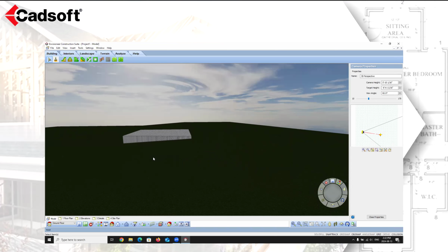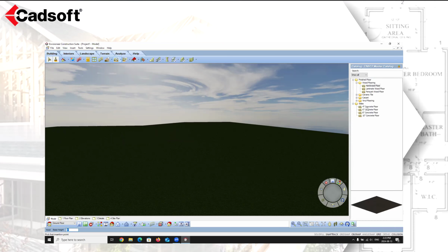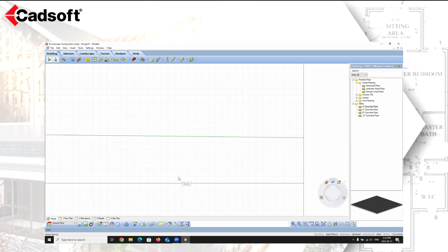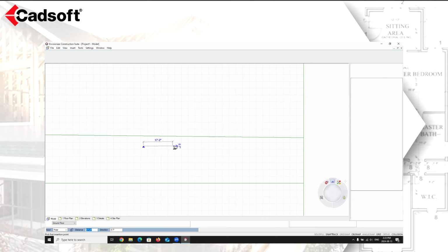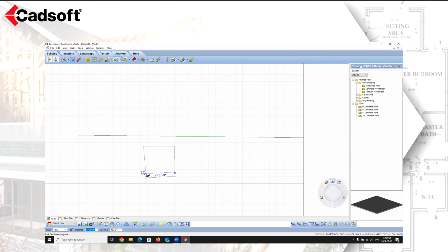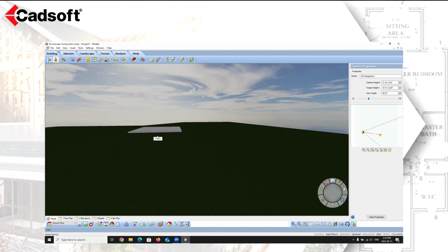The advantage of doing a surface like a floor or adding in a surface itself is you can create an actual thick floor and it will be a true thickness. So here it's trying to fill in that void for us. If you want that to be actually 4 inches thick but be flat, then you would use a floor. And you can use the floor by picking points. And you would just grab your 4-inch concrete slab and you would just say, I want that same floor to be right here, but I want it to be perfectly flat. And I want it to be true at 4 inches all the way through.